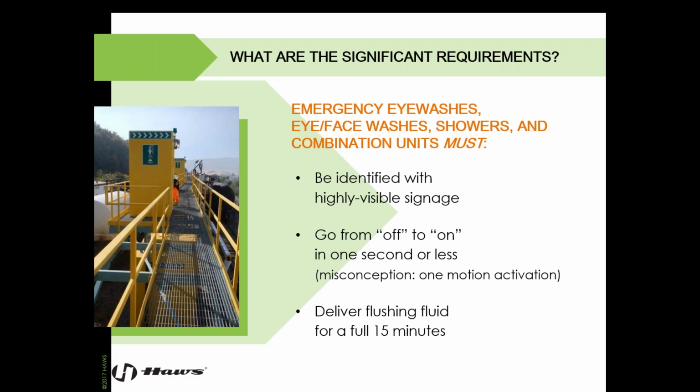All equipment also needs to go from off to on in 1 second or less. This is mostly on the design side as well, but it's important that you're aware of it. There is, interestingly enough, a misconception out in the industry that the equipment or the valving needs to go from off to on in one motion. We hear that a lot when we're at trade shows and through these webinars, and we're here to tell you that we've looked back at all the revisions of the ANSI Z358.1 standard, and not once has it mentioned one motion activation.